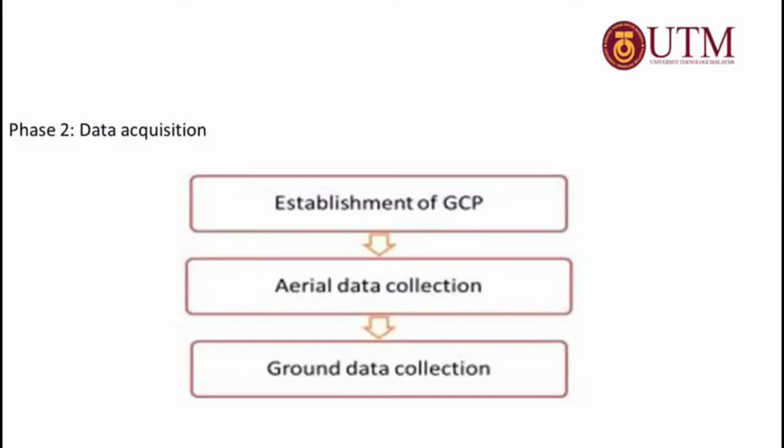It is also important to plan the flight before flying, as it is one of the important aspects in aerial mapping. Flight planning includes weather and ground condition and time frame of photography. Mission must be carefully planned and executed according to the flight plan. A clear weather was determined and chosen. The UAV was flown on the day. A very careful planning for data acquisition is needed in order to avoid the problem of loss and cost.